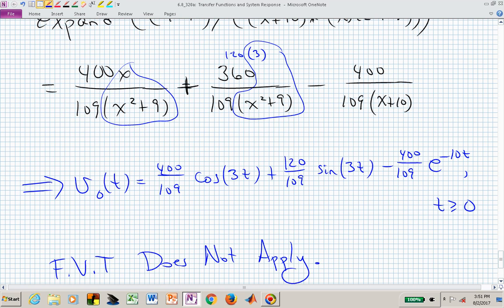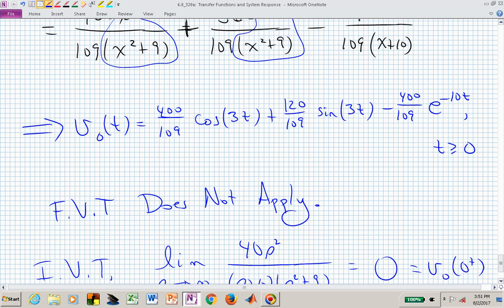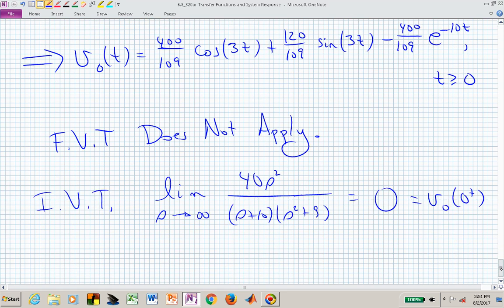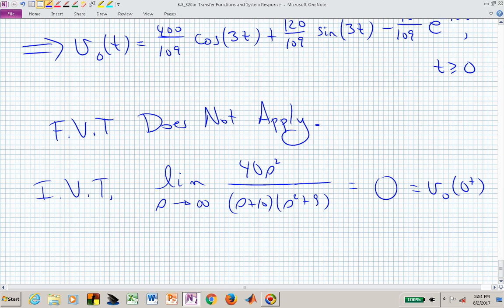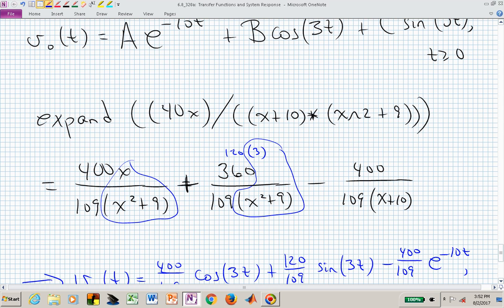That third term in this expression for V sub 0 of t is gone, and we're now just left with these shaking cosine and sine, or we could combine that into a single cosine waveform with a phase shift. So this makes sense that we're starting at 0, and then we just oscillate back and forth as time evolves towards infinity. And now we can see that we can do a lot of analysis with the machinery that we now have in the form of Laplace transforms.